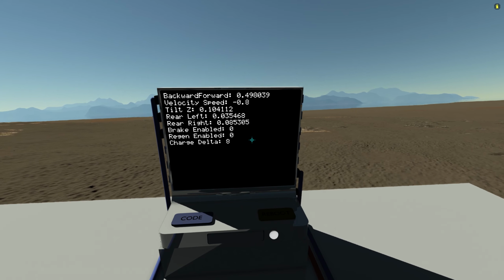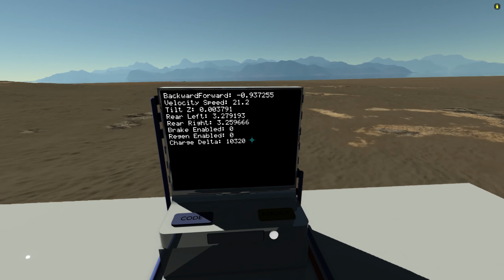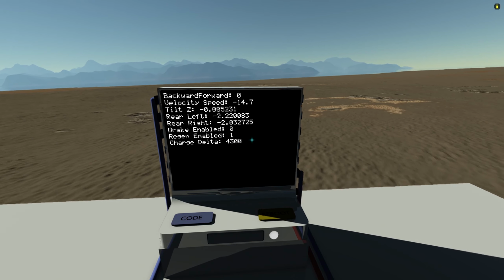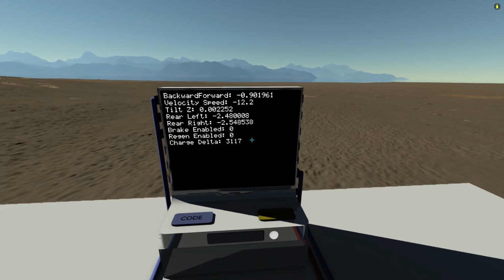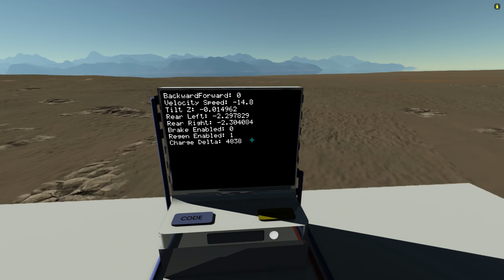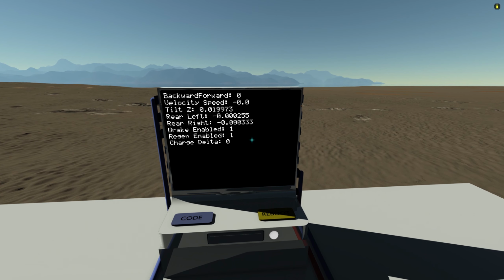So one thing I need is anti-traction slip on here, so I can keep maintaining a straight line. Hit the brakes right here. And this is some of the really advanced stuff you can do. For example, there could be logic in here that if I'm going forward or backwards and I'm not applying steering, then maintain a straight line to deal with that traction loss.